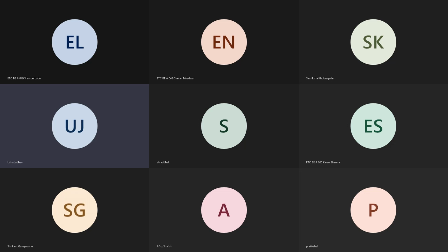With these 4 different mode selections, we'll discuss how to implement the universal shift register using the Xilinx tool. We'll write the VHDL code. We'll simulate it using a test bench. We'll synthesize it. After synthesis, we'll observe the RTL schematic and the technology schematic, and we will implement this universal shift register on FPGA, that is Spartan 3 XE 3S400.